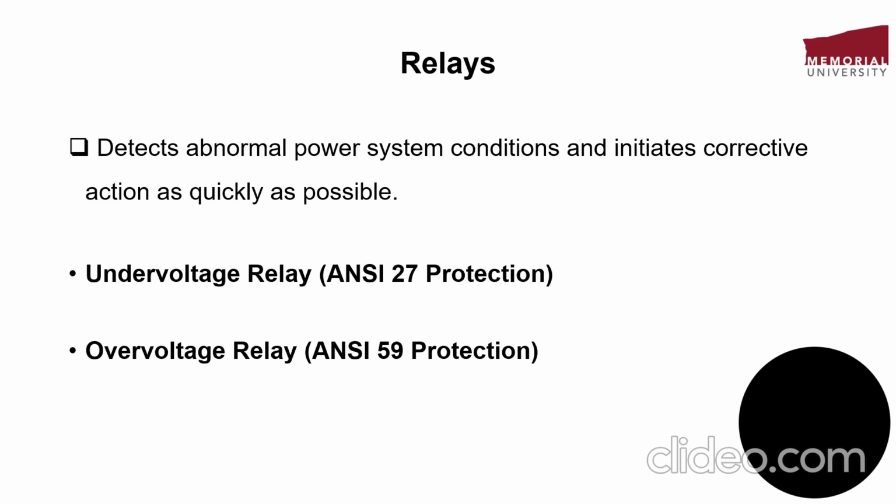As compared to the mechanical relays, the solid state relays do not have mechanical moving parts that the mechanical relays with contacts do. Instead, they consist of semiconductors and electronic parts such as MOSFETs, IGBTs, and transistors, etc. And on the basis of these semiconductor devices, they receive the signals, either voltage or current signals, and perform various operations in the electric circuit.